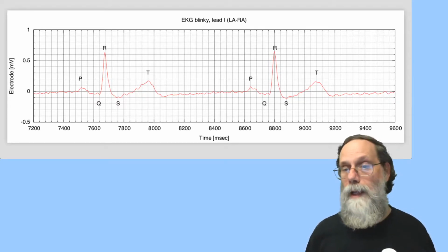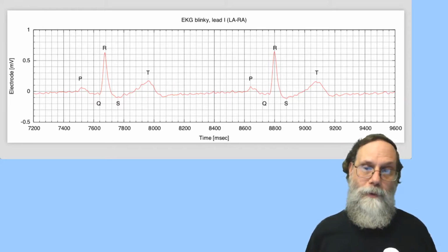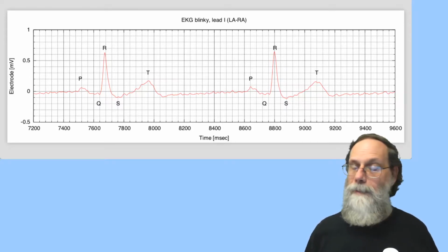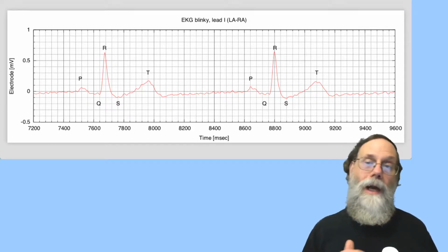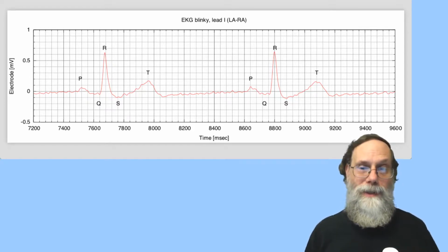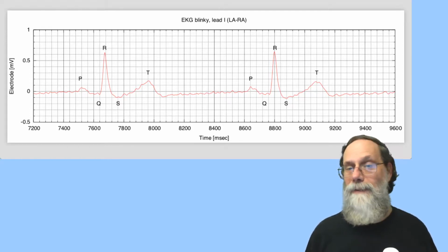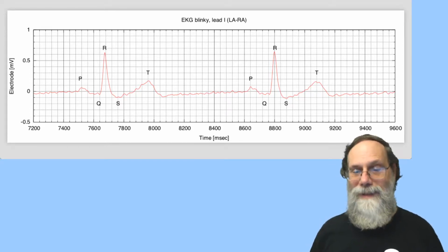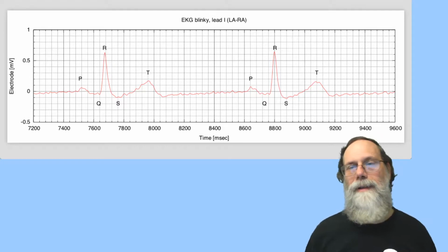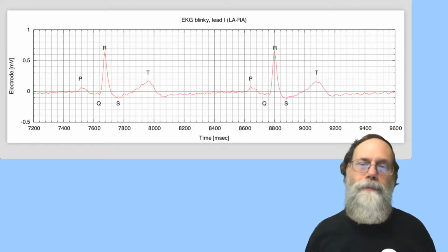This is the same sort of layout that you did for the microphone preamplifier. Figure out which amplifier, which op amp on the quad op amps, is which for your wiring. Color code your wires so that you can easily debug it if there's a wiring mistake. You don't want just a tangle that's impossible to figure out what's going on.